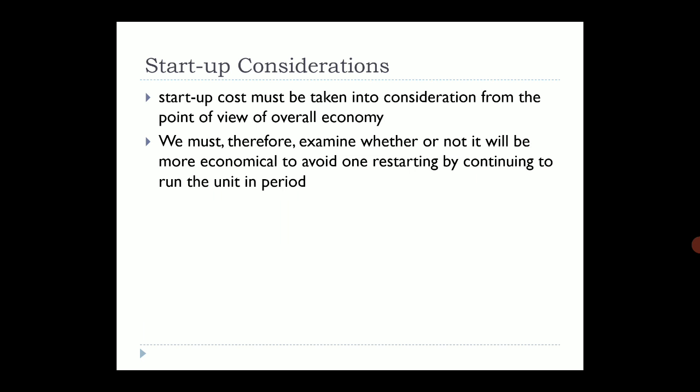So we must examine whether or not it will be more economical to avoid one restarting by continuing to run the unit in the period. So that should be a consideration, whether we keep the generator running without any load, or stop the generator and start it later, because there is a huge starting cost.